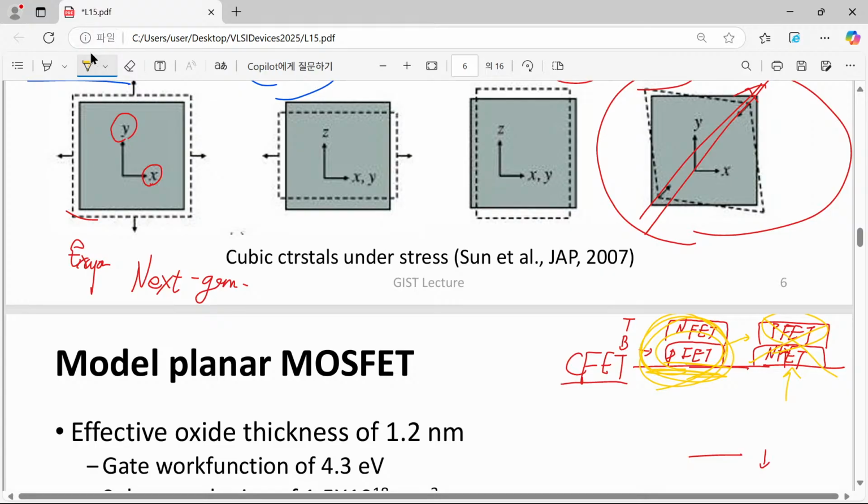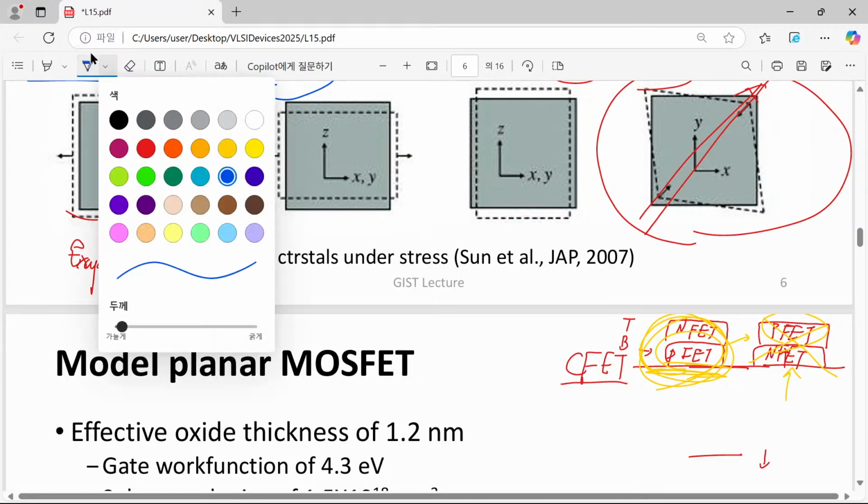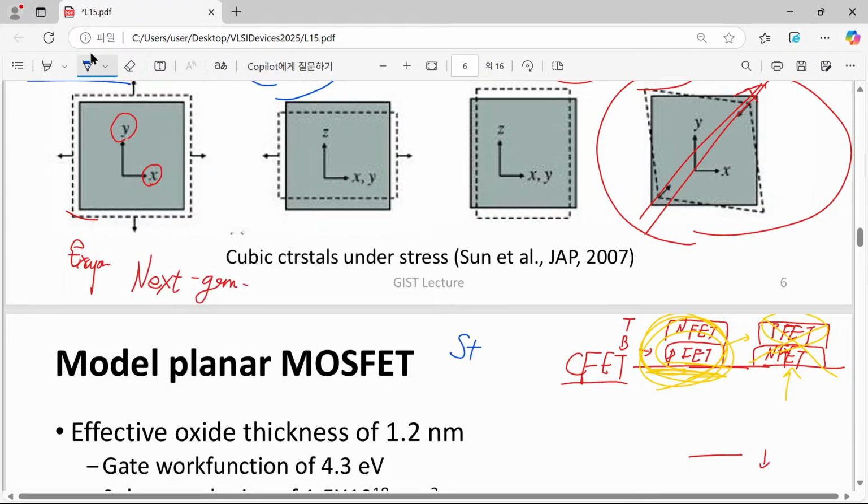So nowadays, what researchers are currently doing is also introducing stress to our 2D materials. For example, MoS2, not just mere MoS2, but strained MoS2 is being investigated, and it is found that actually we can get huge improvement in its mobility. So since we can play with strain and play with mobility, maybe that is an interesting research topic for further technology development.